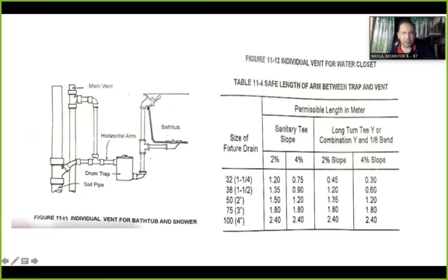When you open this one, it fills water. This is the discharge here, the overflow. You have also the drain here. But sometimes the drain is closed, so it's overflow, it discharges here. But if you want to discharge the entire water, you can use the drainage there. You can throw away the water to the main soil line, going to the main line.